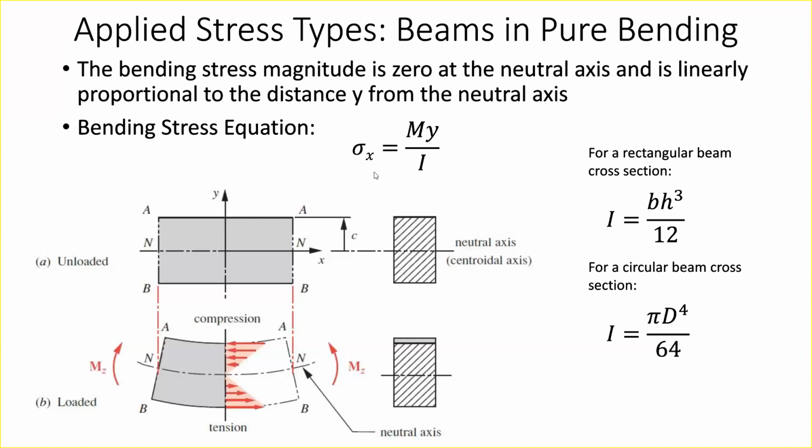So the general equation is that the stress at a given point is given by the moment load times y over I, where I is the moment of inertia. This is the geometric dependency of the loading I was talking about. Again, you don't need to know too much. There are very standard formulas for computing the moment of inertia of standard shapes, and you just plug it into the formula. As a function of y, your vertical position along that cross-section plane, you can predict the amount of stress on that plane. It's a really fundamental equation, but you can use it to predict things like loading on your upright or a whole bunch of different parts on the car.